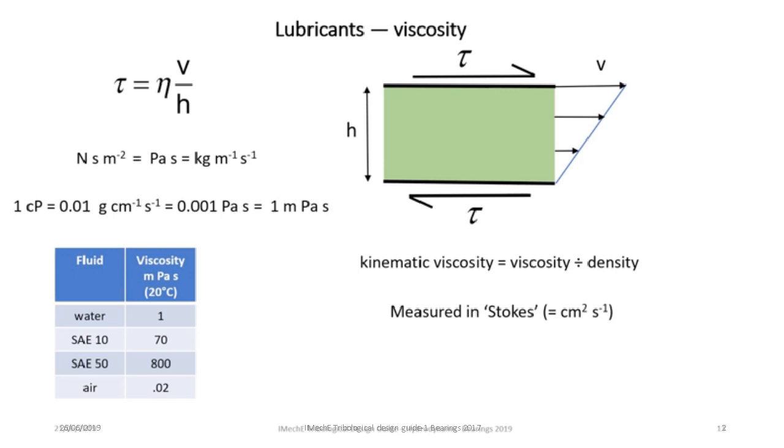The so-called kinematic viscosity is defined as viscosity divided by density, and in the CGS system, the unit is called the stoke. Since mineral oils have a density or specific gravity of just less than 1, the numerical value of the viscosity of an oil in centipoise is quite close to the numerical value of its kinematic viscosity in centistoke.